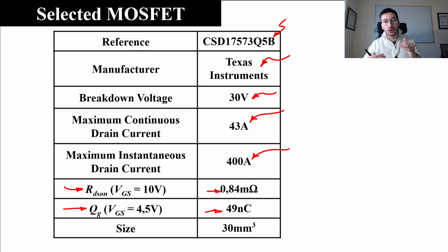If you have a low total gate charge, you will have in general low switching losses, because you need to put less charge into the gate to source capacitance in order to turn on the device. So, let's say that you have a faster device. If you have lower total gate charge, you have a faster device that is able to turn on very quickly with less charge.